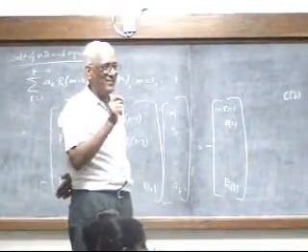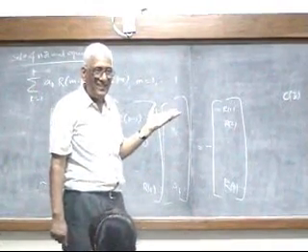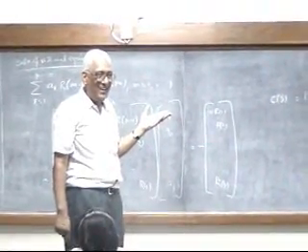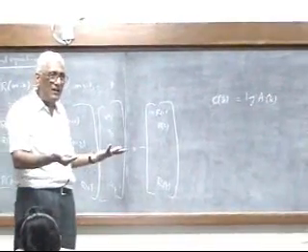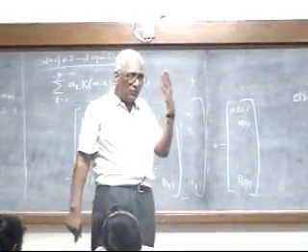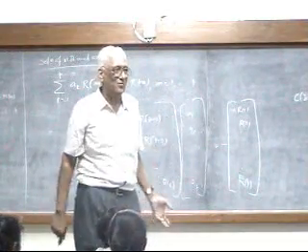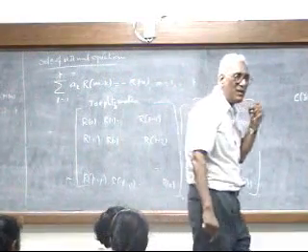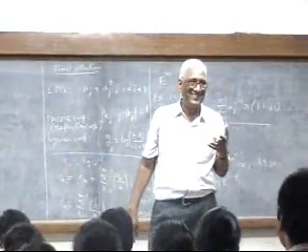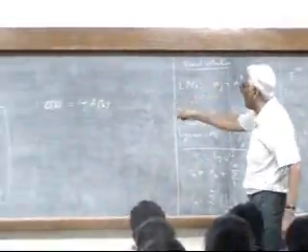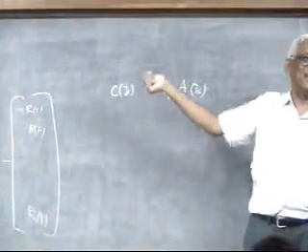Exactly. If I give any hint, log. You remember we have taken the log earlier? And when you take the log and express that as an inverse Fourier transform, what is the inverse Fourier transform? It's nothing but simply a polynomial again. Don't look at a Fourier transform as something very difficult. It's nothing but a polynomial only. Fourier transform also is a polynomial. Why? Because of e to the power of j omega n. So I have a polynomial, I take the log and then get the coefficients of that polynomial. So that is why it becomes this.